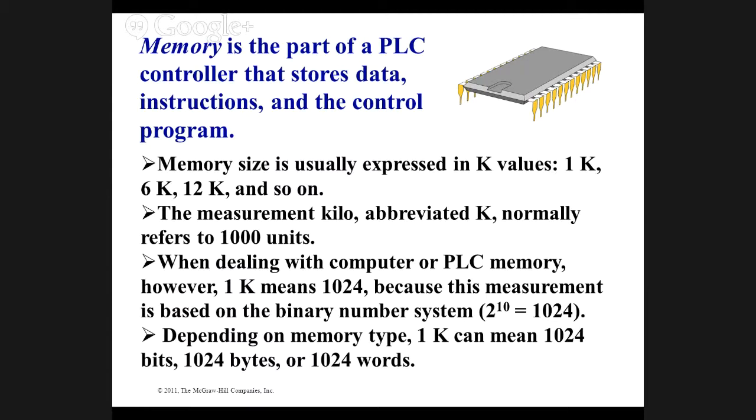Memory, you can run out of memory in the old ones. You used to have to worry about that, but now they put megabytes, and some of the controllers come standard with 32 megabytes. That doesn't sound like a lot, but when we're talking ladder logic, that is a massive amount of code you can put in there, because these programs don't take up much room. The one you had in your hand was probably 512K. That holds as much as one of the old floppy disks, the big 5-inch ones.